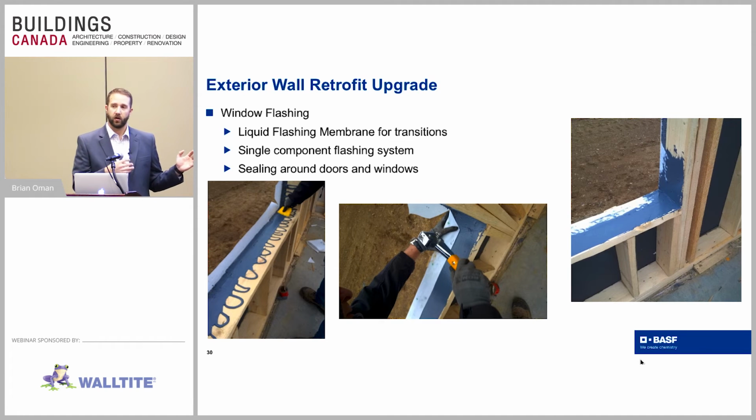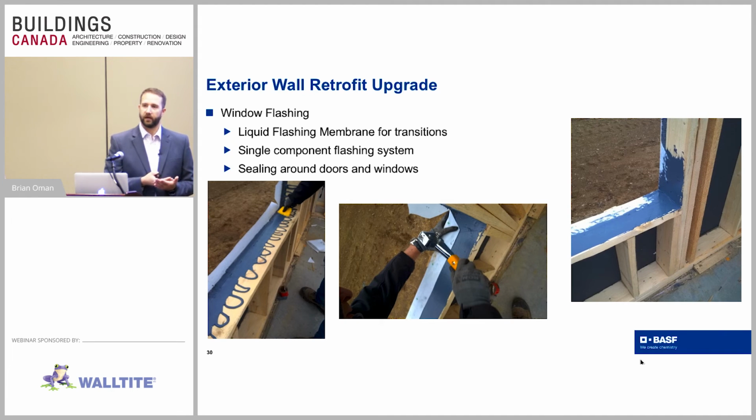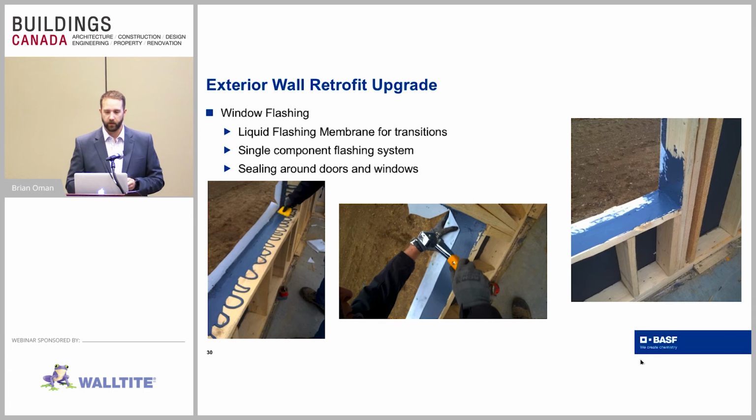This can be done also if we don't have that exterior wrap. We would just take the sealant and wrap over the edge and out onto the face of our exterior foam. Once our windows go in, we can now integrate our window directly into that weather barrier, that sealant that's now been spread onto the face of the exterior foam.